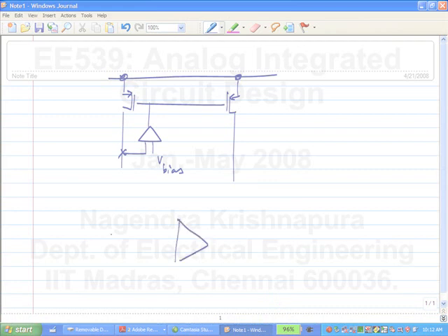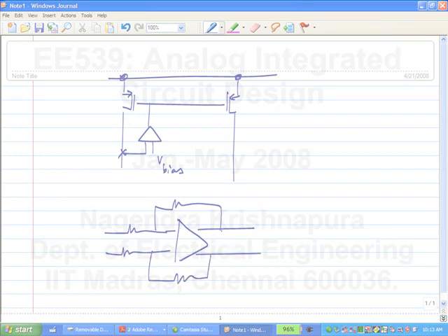Let's say I make an amplifier, the usual inverting amplifier. If I want the output common mode to be different from the input common mode, I need to have some voltage like this in quiescent condition. I need to have quiescent currents flowing through these resistors. That's usually not done. You can do it, certainly, but it's a waste of current, and frequently the devices you use to draw these currents also tend to add noise.